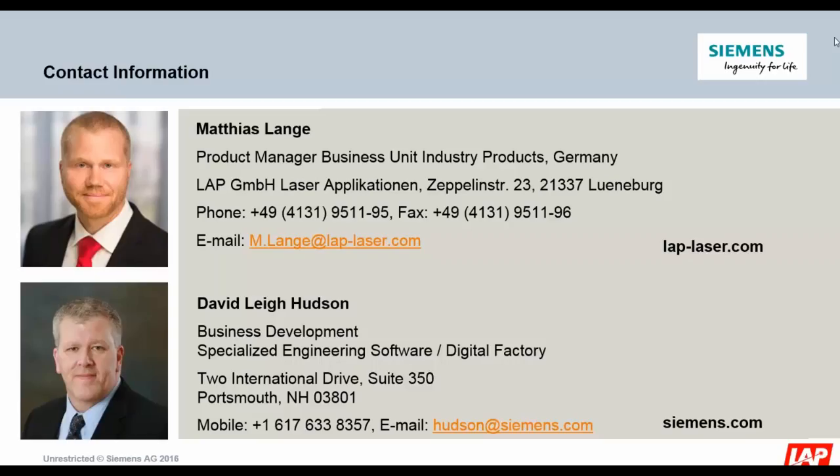But in terms of what we do from a design to laser standpoint, from ensuring that what's being laid up is being laid up accurately, we actually take into account the ply thickness as we generate the laser projection data. In terms of tolerances, that's very dependent upon the design itself.